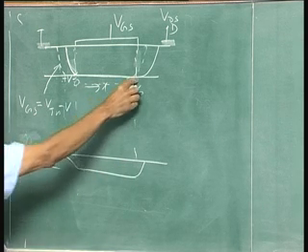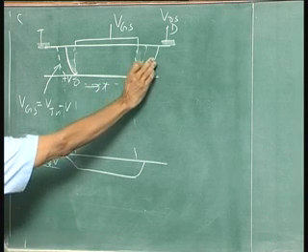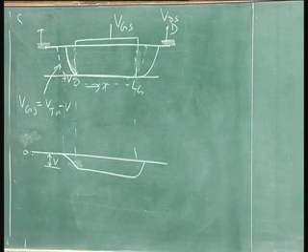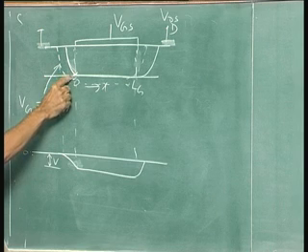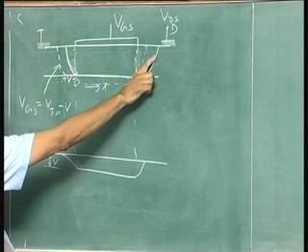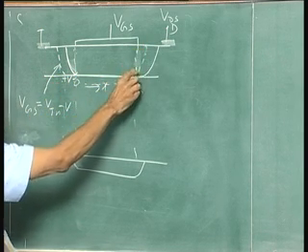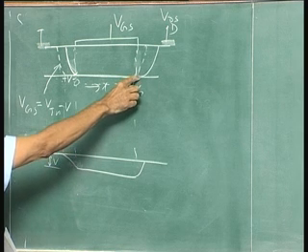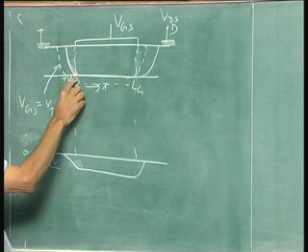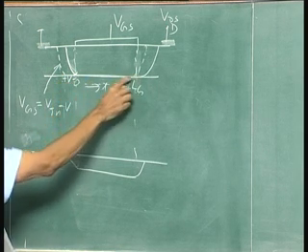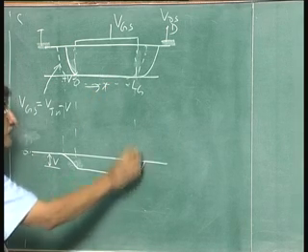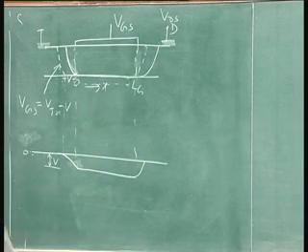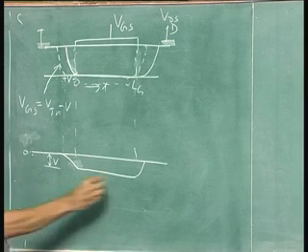But because the drain voltage is there, if the drain voltage is 0, there is a drop here, plus to minus, and when you come down to this point, if this is not there, the depletion layer would have been here. What will be the potential here? Plus minus, minus plus, 0. So, it would have come down like this, but you have got an additional drop VDS. So, the whole thing will be like this.